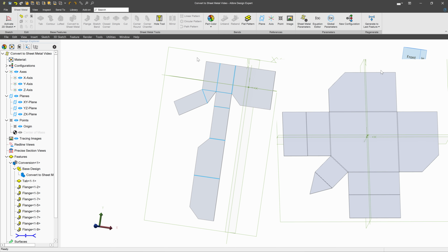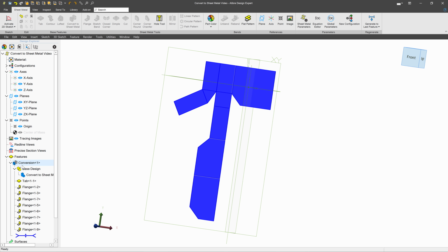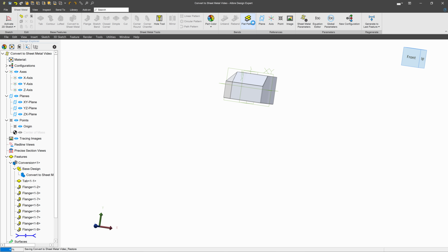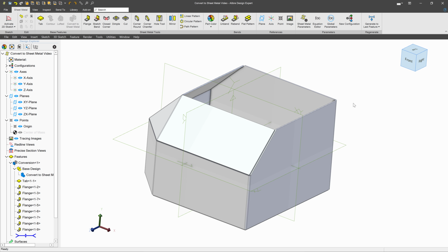You'll also notice that I'll require a different size of sheet metal blank to start out with. So depending on how I choose my bends, I can start out with a larger or smaller piece of sheet metal and have more or less waste. So being able to edit down the tree like this and change the way that we generate our sheet metal part is greatly beneficial, because we can always make changes that save time or material as we go.